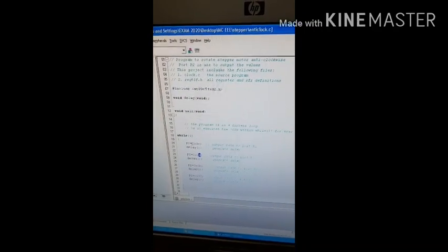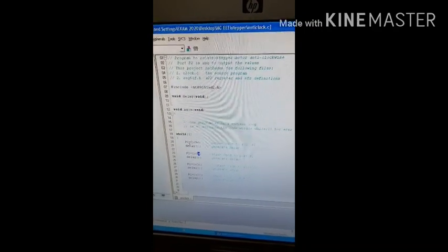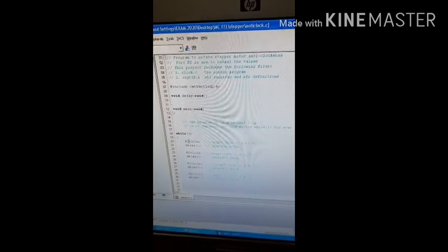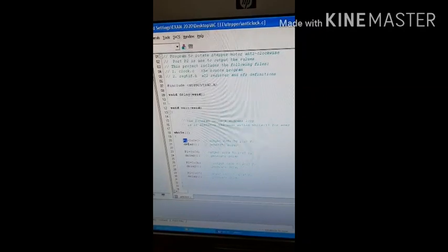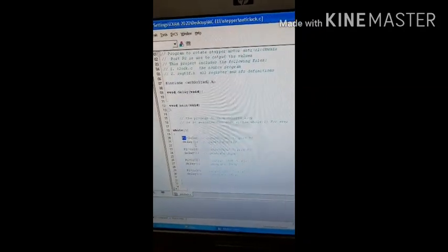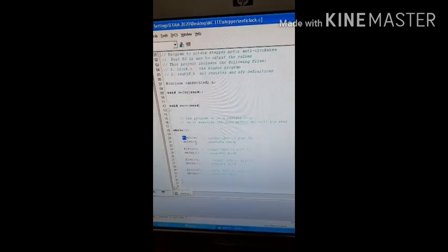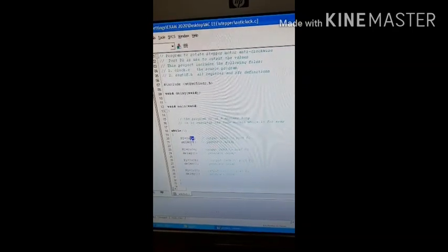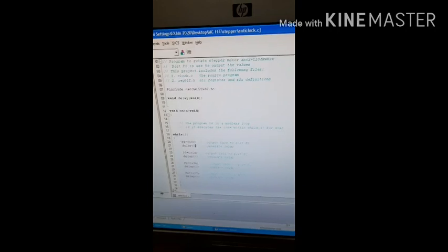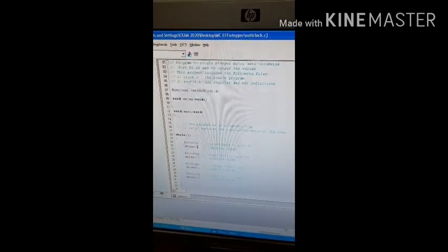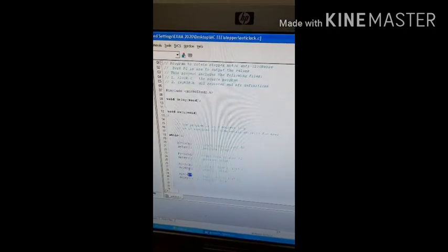These codes are ported to the interfacing circuit of your stepper motor by means of port 2, and after each code is ported out, a suitable delay is introduced. This is the first code followed by a certain delay, this is the second code followed by a delay, this is the third code followed by a delay, and this is the fourth code followed by a delay.